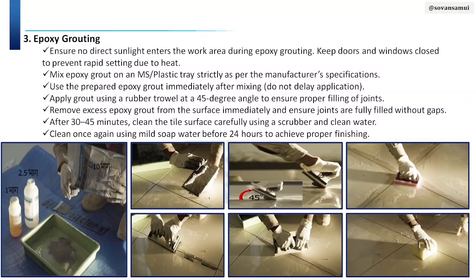Next point is epoxy grouting. In epoxy grouting, I have prepared some visualized content that will help you understand. It is the actual standard procedure of how epoxy grouting is done, and there are some precautions also, such as ensuring no direct sunlight enters the work area during epoxy grouting. We should keep doors and windows closed to prevent rapid setting due to too much heat from sunlight.